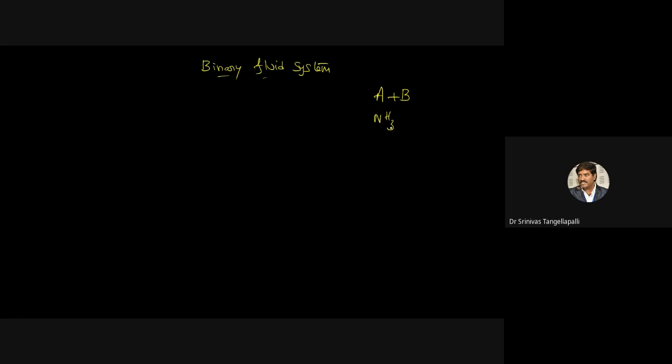If you want to reject the heat at 30 degrees centigrade, NH3 alone, for power or cooling, needs nearly 8 to 10 bar pressure. At the sink, I am saying, not at the source. Maintaining high pressure is difficult, and maintaining a very low temperature for heat rejection is also difficult.